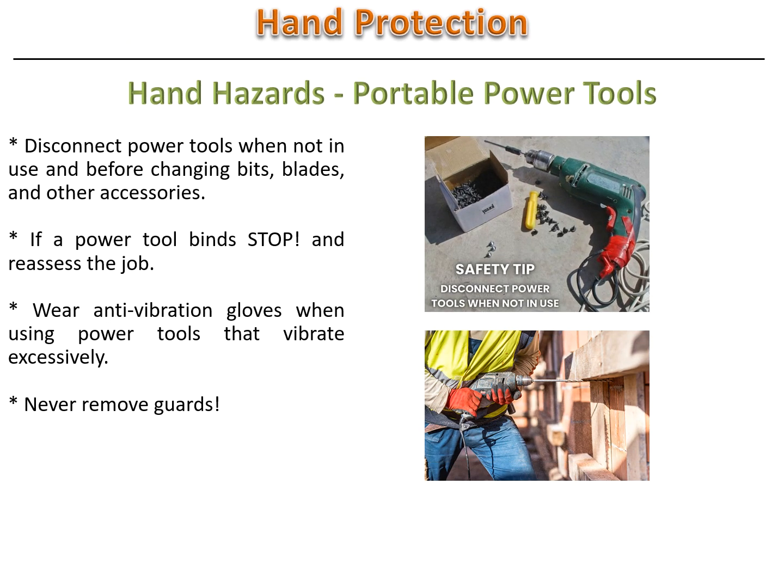Hand hazards, portable power tools. Disconnect power tools when not in use and before changing bits, blades, and other accessories. If a power tool binds, stop and reassess the job. Wear anti-vibration gloves when using power tools that vibrate excessively. Never remove guards.